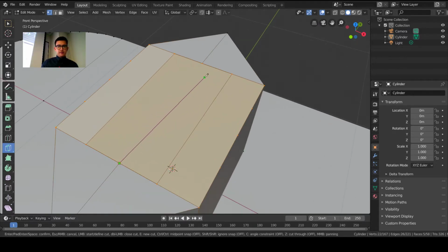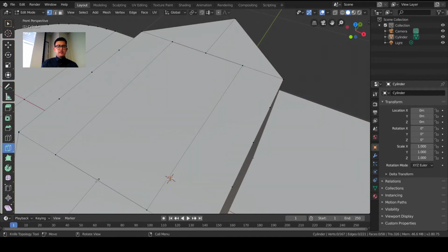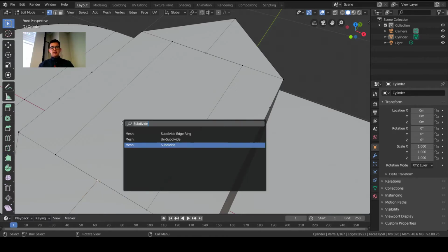I'll make a cut here also. Okay, that's fine. So what I can do is just render a circle here and there, and I'll try to get them not all the way touching to here. So I'm going to go to vertex select mode, select this vertex, and then type the command snap cursor to selected.